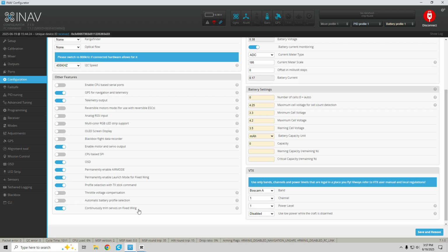I do not like that. I like my yaw at center and level. And so when I want to dive quickly or turn quickly, I have full throws and I have nothing stabilizing my yaw. My yaw works perfect that way. That's the way I do all my planes. No stabilization on yaw, even on regular planes with a regular tail. That's pretty much it on that, guys.